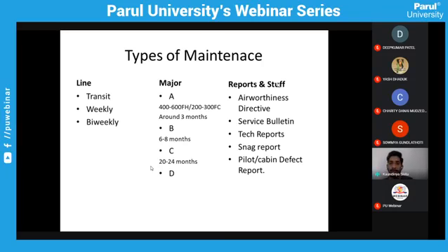all of you who have flown in an aircraft will have sat in the seats, right? Next time you go, just check the bottom of the seat. There will be a track, like a train track, a seat track where the seat is inserted. Recently, there was a directive from the DGCA saying that there is a fault in some of those repairs.